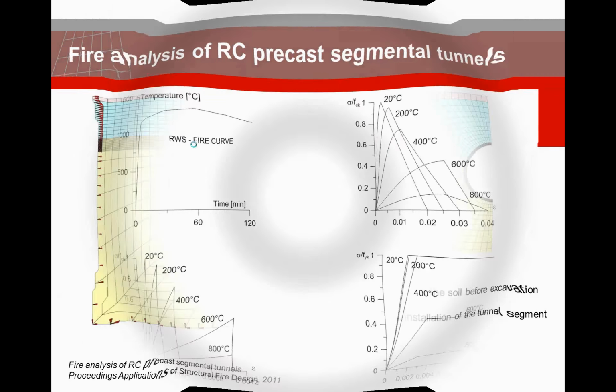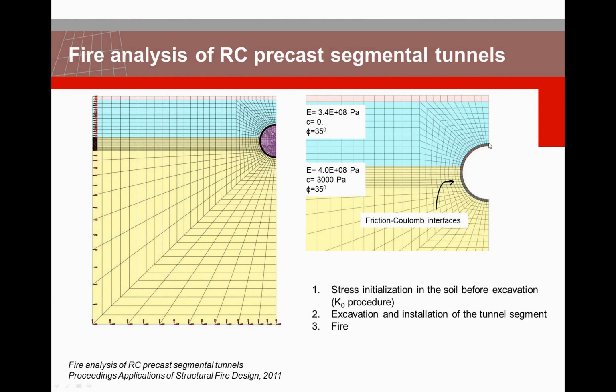There is one more thing here, which is the soil structure interaction. So we define a kind of interface between the tunnel lining and different soil layers here to cover the full interaction between the nonlinear behavior of the soil and nonlinear behavior of the tunnel lining, because this fire is going to induce a series of expansion loads in the model, while the whole model from the top surface is subjected to the traffic load. This is one of the high-speed underground train tunnels, and the authority were asking for the effect and impact of a 2 hours fire inside this tunnel.